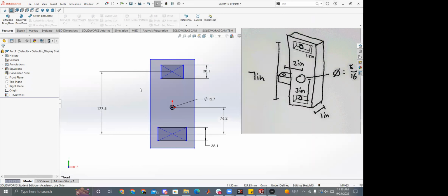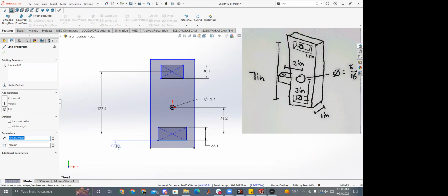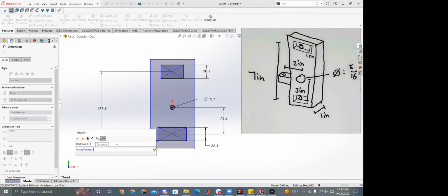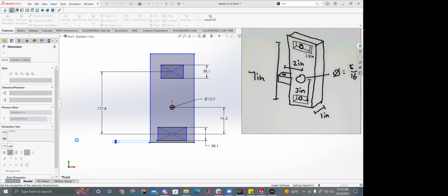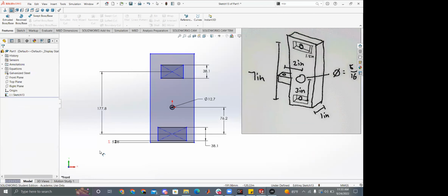Okay, so now that's defined. So now if we take this truss thickness, we define it here. Also something important: if you just put the name of the global variable, then it will just read the value and put it in there. If you change that value later, it won't actually update in the model. What you need is an equal sign and then the global variable, like that. Then when you click off of it, it will have that red sigma. That means it'll update as the variable updates.